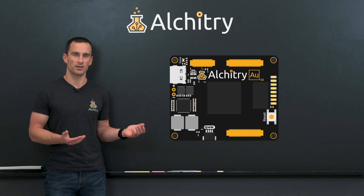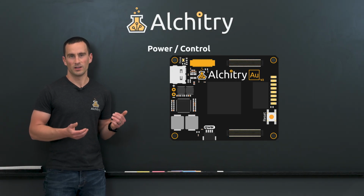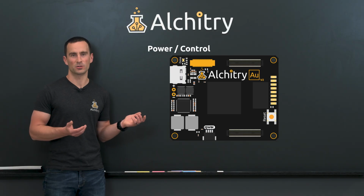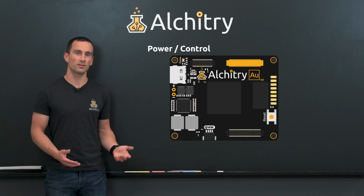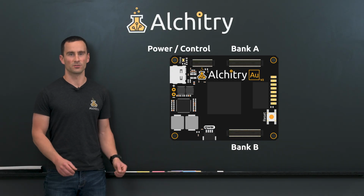There are three connectors on it. The small 50-pin connector in the top left is the power/control header. It has signals for power, programming, and other special control signals. The top 80-pin connector is bank A, and the bottom 80-pin connector is bank B. These are where most of your signals are routed through.